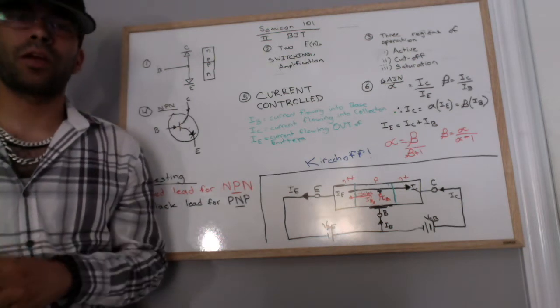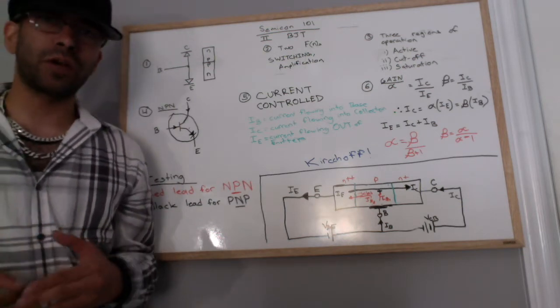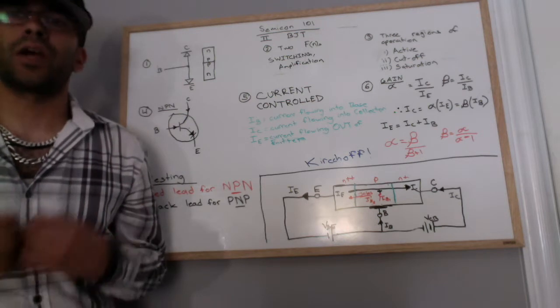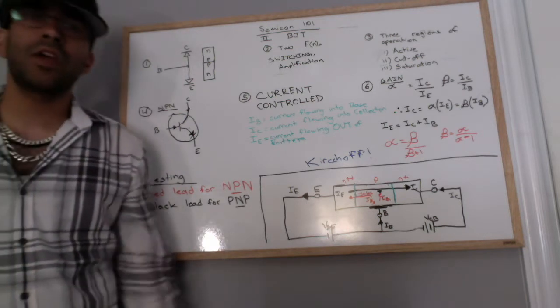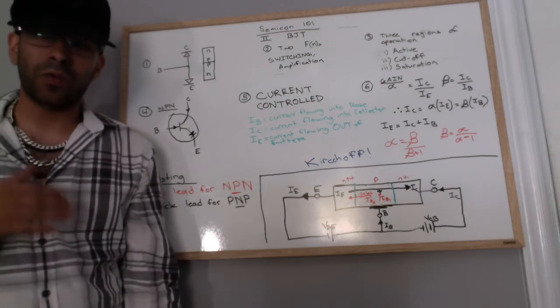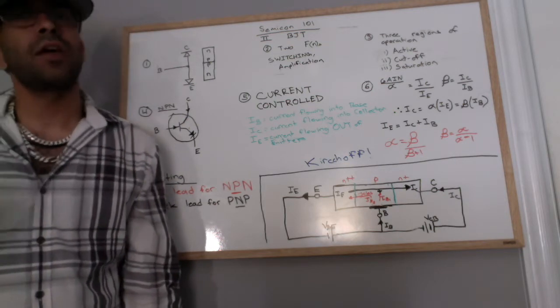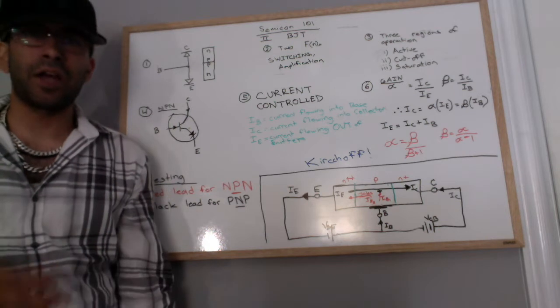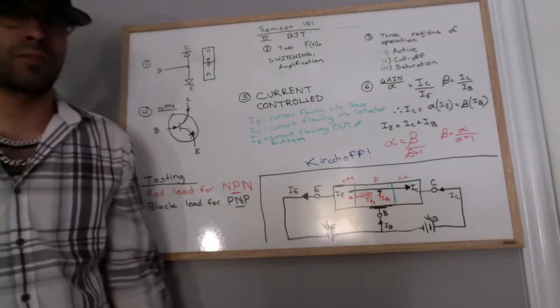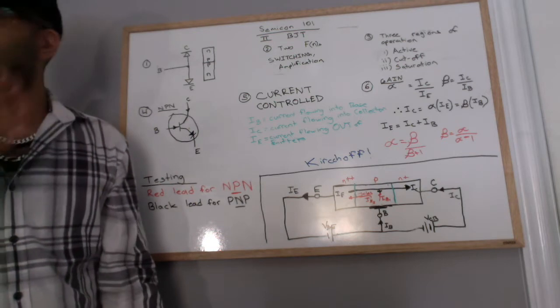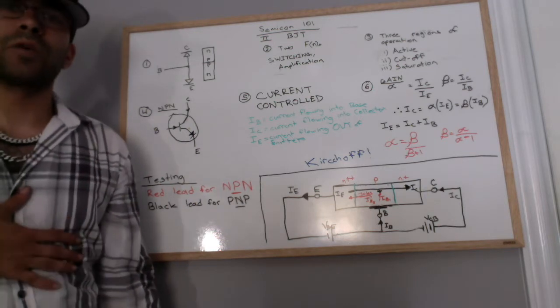I discussed diodes and Zener yesterday, the PN junction, depletion region, and barrier potential. All these concepts are fundamental to understanding transistors because transistors are a semiconductor device just like diodes, and in fact, one of the simplest ways we can model transistors is using the two-diode analogy. This is taken straight from Caltech and almost every other textbook on Earth. It's not a perfect model, but it'll give you an idea.